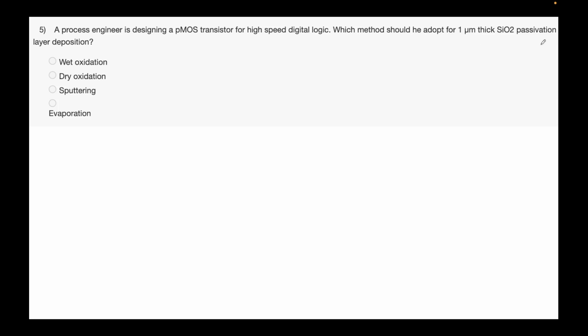So we want to passivate. What is passivation essentially? Put very bluntly, let's say this is the source, this is your drain, this is your gate. And this is the metal contact, let's say, that we have, and this is one more metal contact that we have. You want to protect the rest of this area, let's say at least this area. So you deposit some silicon dioxide on top of it, so that this surface, this leakage mechanism, remains as pristine as possible. That's what we mean by passivate.